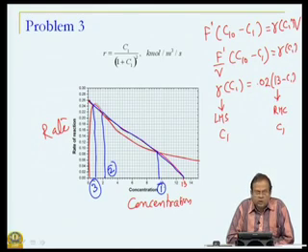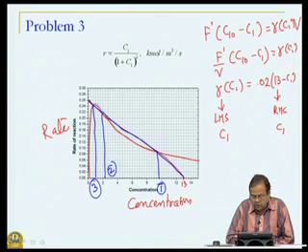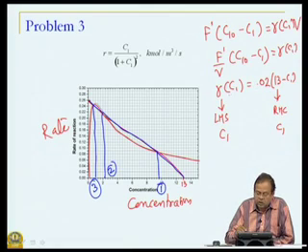Now, in this particular case, I will not go into the maths, but you can work it out yourself about the stability, for example. Remember, when we talked about isothermal non-isothermal reactor, we said that for those conditions under which rate of energy removal is higher than the rate of heat generation, we had a stable steady state, and when the heat generation slope was higher than the removal, we had an unstable steady state. Here there is no energy removal or generation, but what is it? It is mass generation and mass removal.